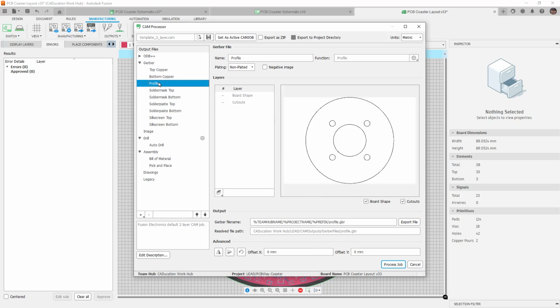I then want to do things like double check the profile. And the main reason for this is because oftentimes when you're generating the shape of your PCB inside of Fusion, if you're not doing it as a sketch in the design workspace, you may find that the way you create these circles aren't actually defined as holes through the board. Now, I've had this happen to me before where I had a hole that restricted the polygon pour, the copper on the top plane, but I didn't actually have a hole go all the way through the board.